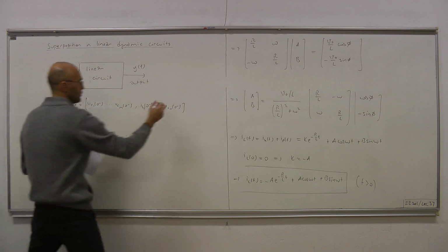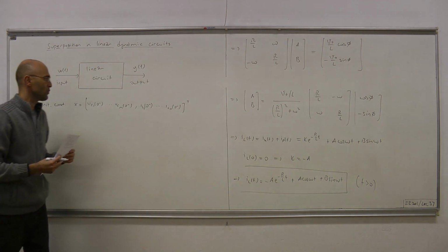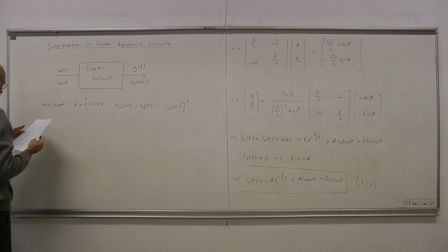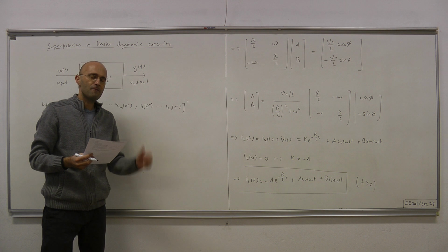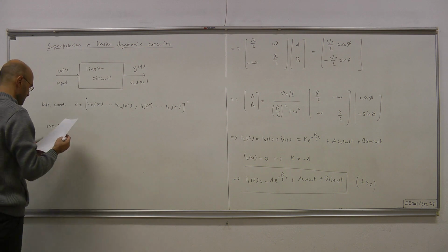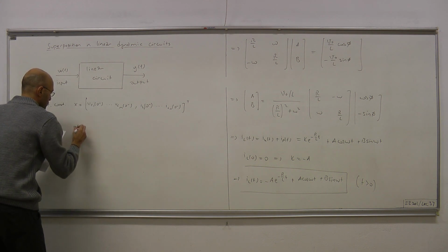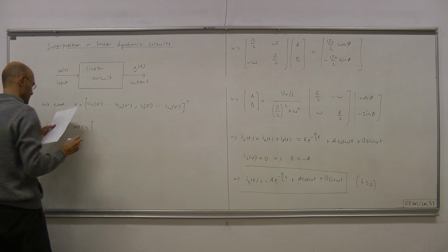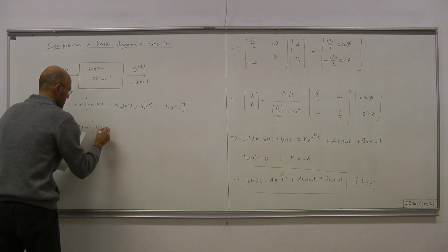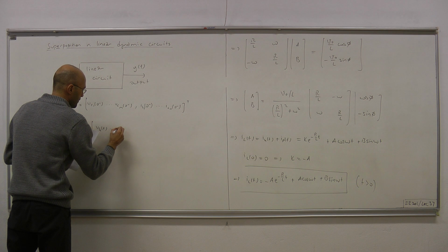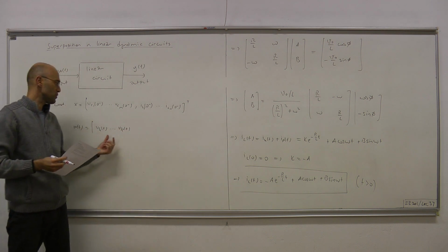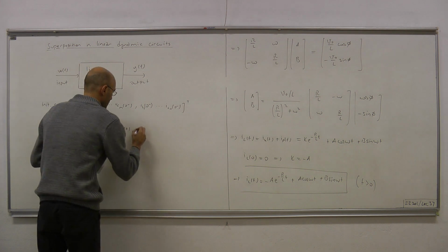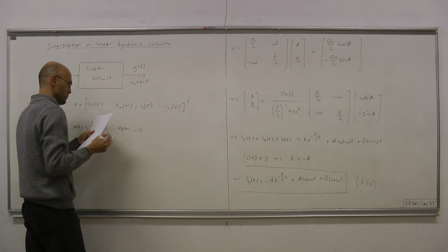We usually work with column vectors, therefore let's transpose that. As for the input, it also is a vector, but its entries are functions of time. w(t) equals [V_s1(t), ..., V_sp(t), I_s1(t), ..., I_sq(t)] transpose. Suppose that we have p independent voltage sources and q independent current sources.